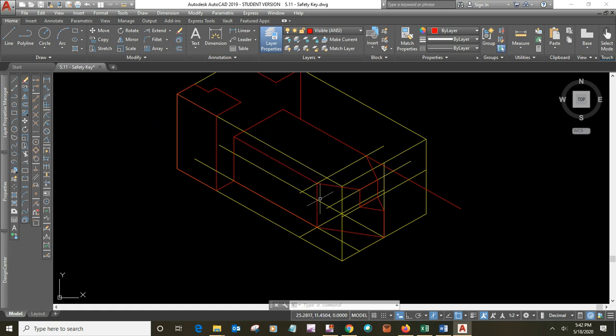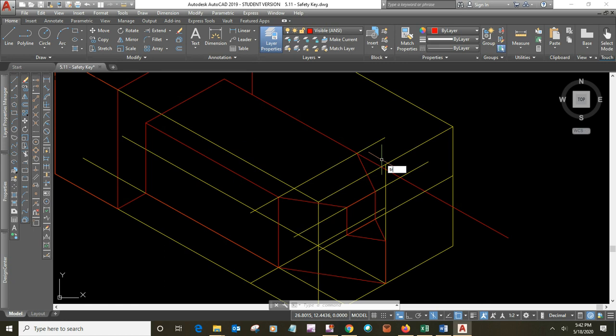Now then, the hole over here, we need a center line for it, and the hole is going to be an ISO circle. Let's see, I'm at 16 minutes. Okay, I'll finish this one out and then split it when I upload it. We need to know the center marks for those things. You don't have to delete your construction lines, and I'd really rather you not delete them. I'd rather you keep them so that I can look at them and it helps me to grade. Oh, I can trim that. I just saw that.